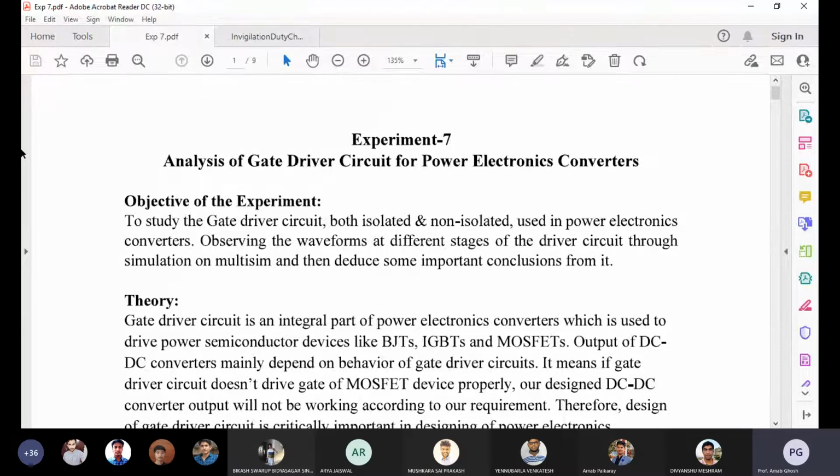The current strength. So what we need to do, we have to add some more for amplifying the current. Okay, we need to add some amplifier circuit. Suppose not exactly an amplifier circuit, but some configurations of signal transistors, suppose SL100, in totem pole configuration or Darlington configuration, whatever is required. You have structured them and fabricated them, and by passing the signal through those combinations, you can get that amplified response. That amplified signal can drive your power BJT.